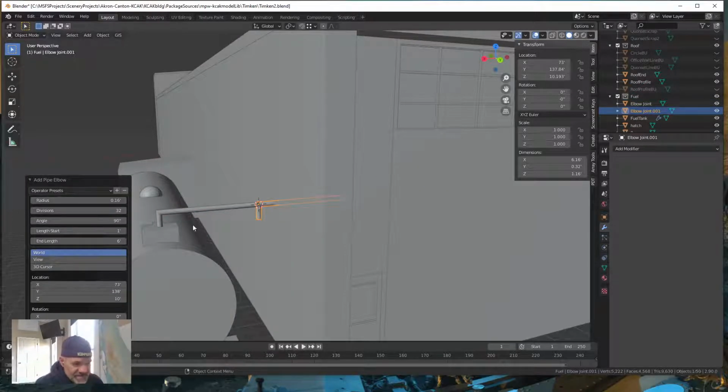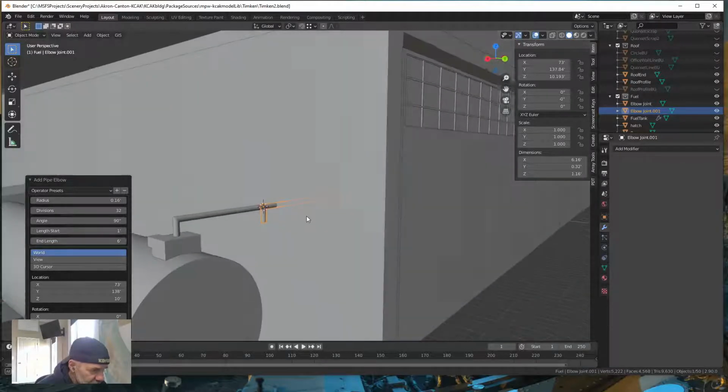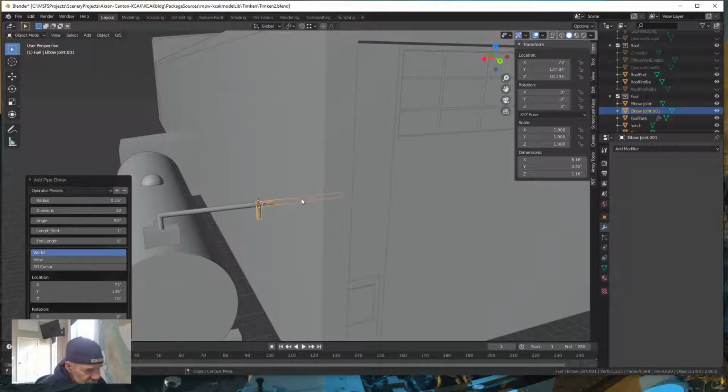Okay, and since the last elbow that we put in had 0.6 feet as the radius, anything that you do will have what you used last time. So we don't need to make any changes. However, we do want this pipe now to pivot, so we can take this end and put it at the end of this one. You with me so far?